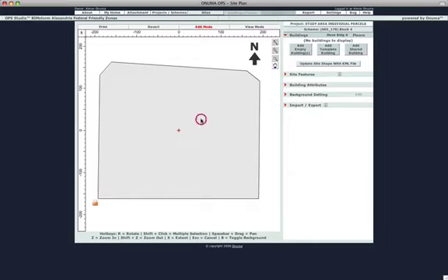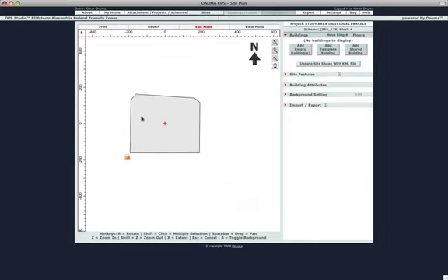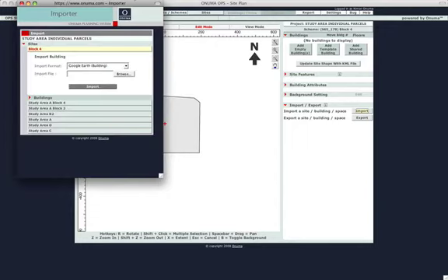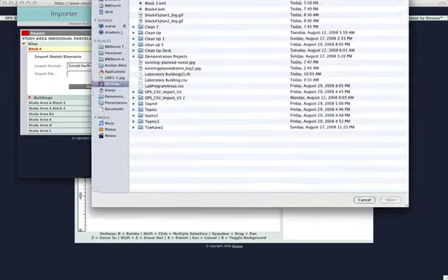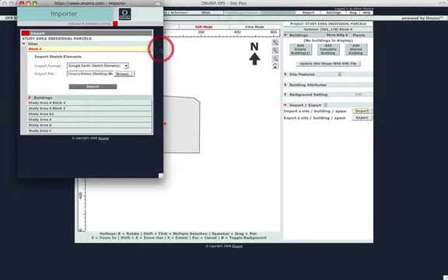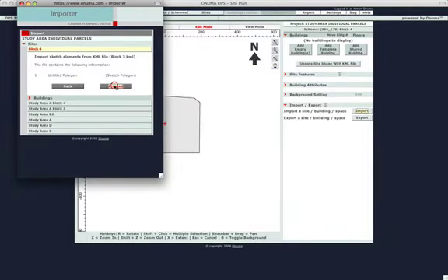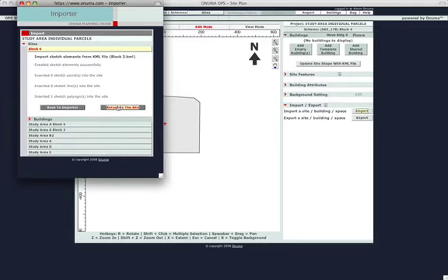Let's zoom out a bit. So we have our primary block in OPS. There always has to be a primary block. Anything else that's imported now is just going to be a sketch element. So I'm going to import instead of update the site shape. I'm going to grab Google Earth sketch element, which could be a line, a polygon, or even a point, and grab this block 3, which will just be a reference next to the block 4 that I'm working on. Proceed with that. Return to site.